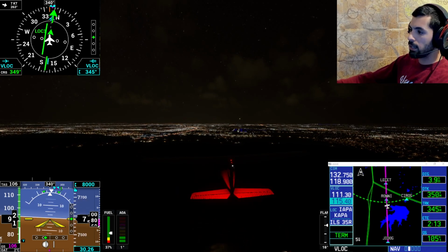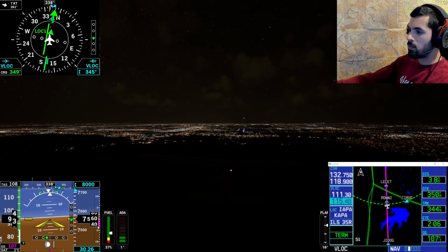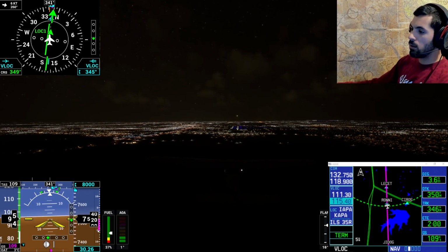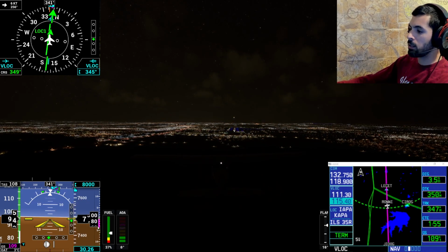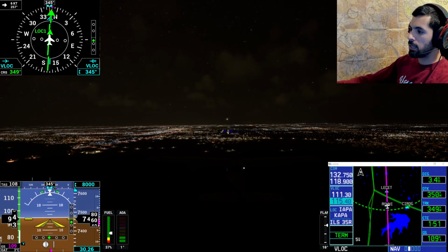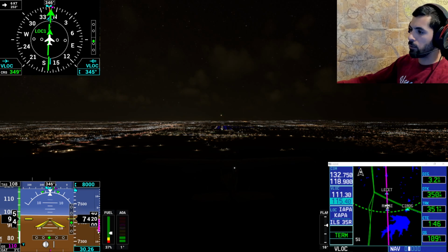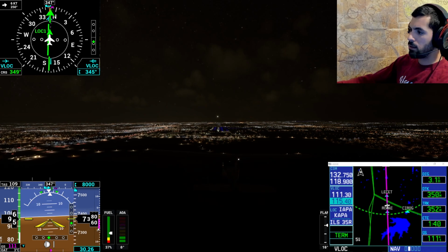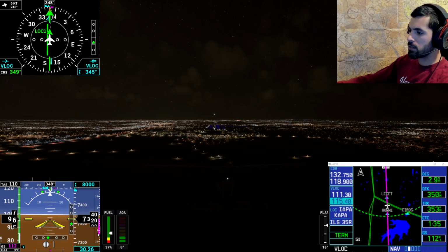And like I said, with the localizer, it's going to get more sensitive as I get there. The same is true for the glide slope. So I really want to be very diligent with these movements. I don't want to make too large of movements because then I'm going to go way off. So trying to look at the headings you're at, what's working, what's not working. If the green kind of goes down, I want to bring that nose down. If the green stabilizes, that's the angle I want, but it's still kind of getting away from us.